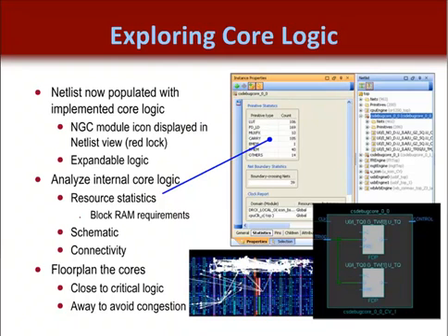One of the other side benefits of PlanAhead is the ability to make effective area constraints. Some customers choose to assign their ChipScope cores to specific area constraints in order to avoid routing congestion or to keep the core near critical logic. However, note that if you test nodes that are very far away from the cores and are assigned an area constraint, then you might incur some significant routing delay. So be careful about placing those area constraints and where you place them on the die.